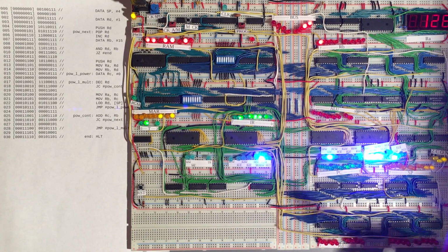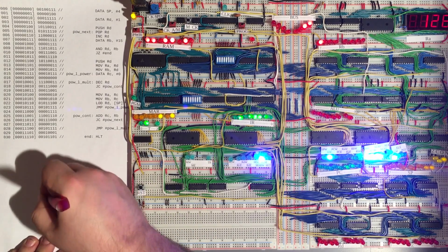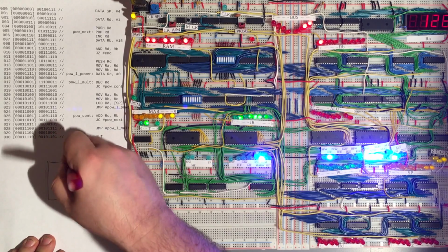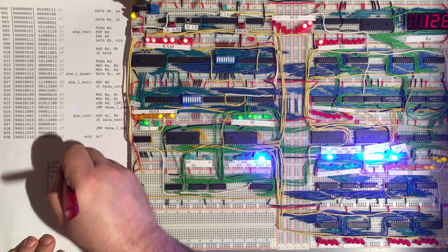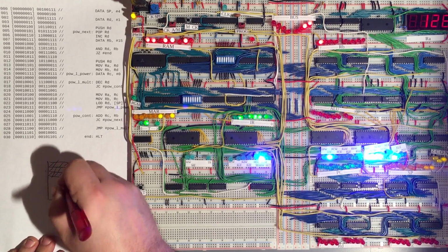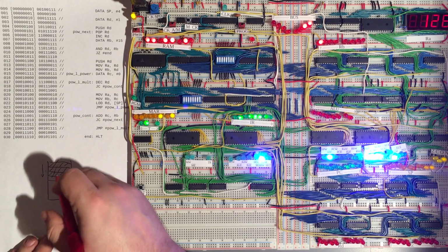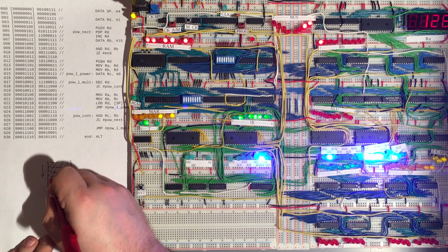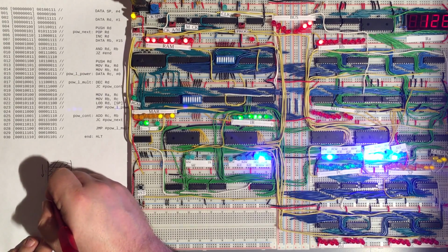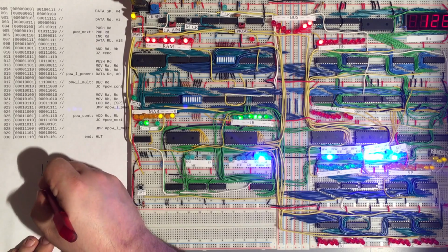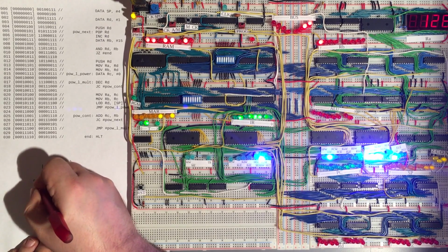The way the stack works is that it's a series of memory locations which grow downwards. As we put values onto the stack, these are occupied cells, and our stack keeps growing downwards. Whenever we write a new value in the stack, we fill this cell here, and then we get ready to use the next one. The stack pointer itself always points at the last cell which contains a value.